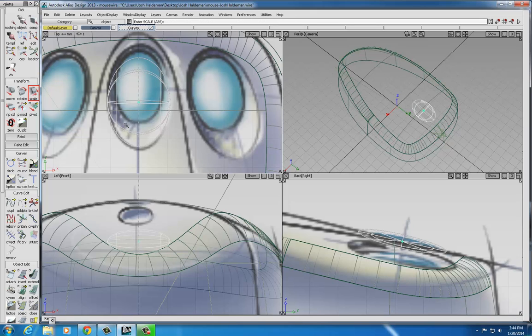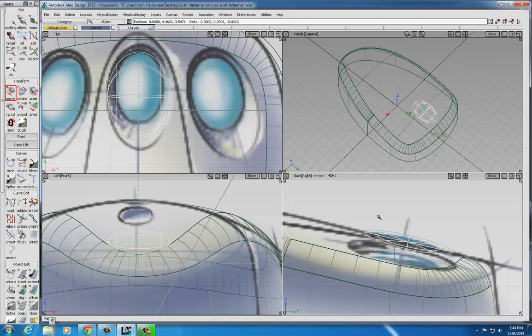And remember, I'm looking to place the size of the housings, not the buttons themselves yet. So look for the recesses for these buttons. Then I'm going to move it a little bit so that it's better centered. And I'm doing that in the side view, being aware of how I'm moving it, not just up and down, but also side to side.